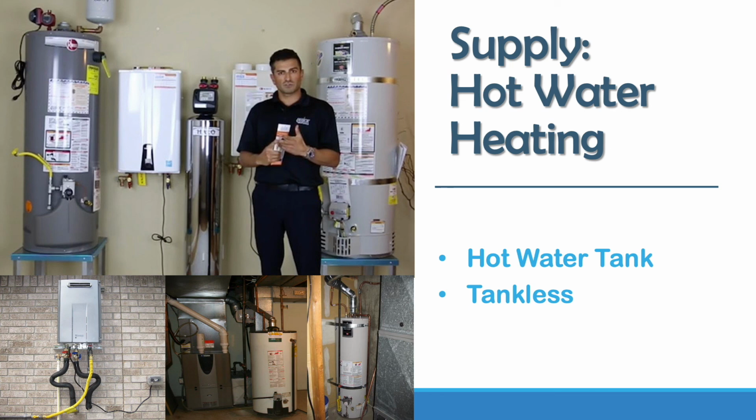Now, a tankless water heater does not hold water in it, but it runs the water through and it heats it instantly. Sometimes these systems can be referred to as an Insta-Hot as well. The output is anywhere between 2 gallons per minute and 8 gallons per minute. Again, you set it to the temperature that you want. Typically 120 degrees Fahrenheit is the temperature.